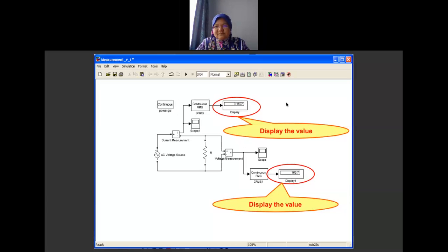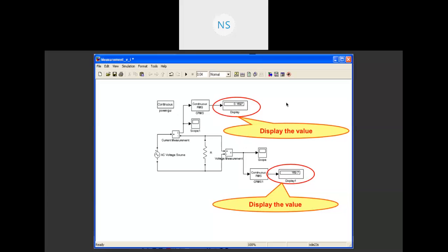It means that you have a problem with your MATLAB installation. You did not completely install your MATLAB tools or software. SimPowerSystems is actually common in the Simulink library browser.